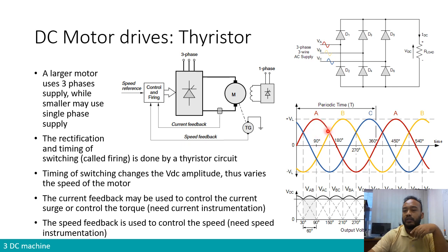It will take into account only the second part of the positive wave. By doing so, the average voltage at the end, when we calculate it, will be slightly lower than the full waveform if the thyristor started operating at 0 degrees at the beginning.